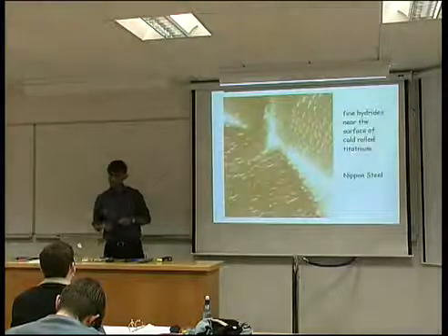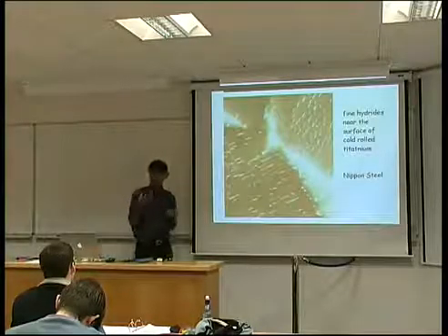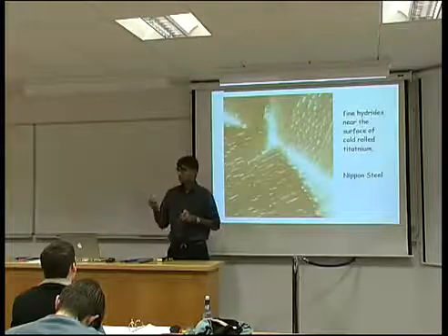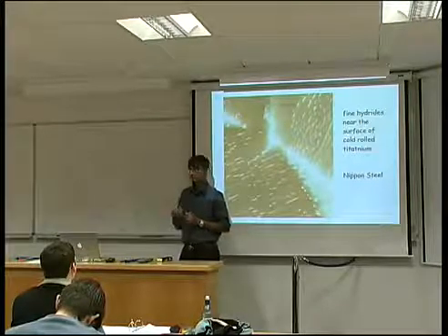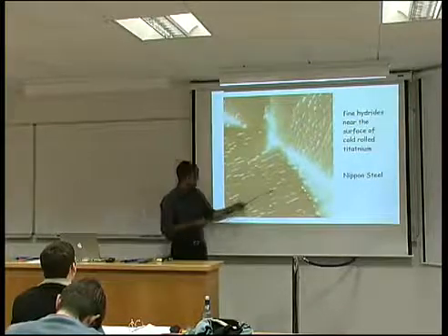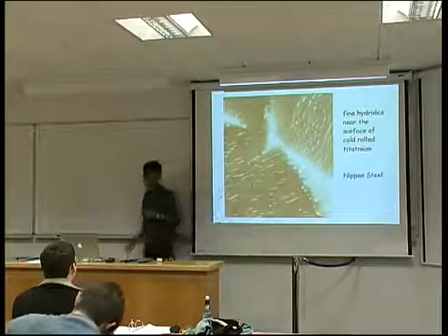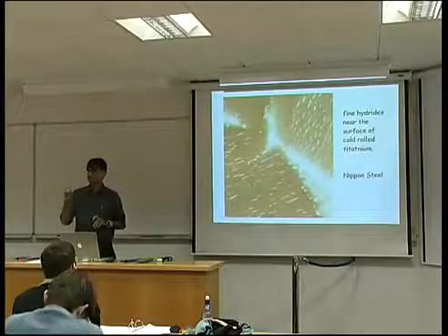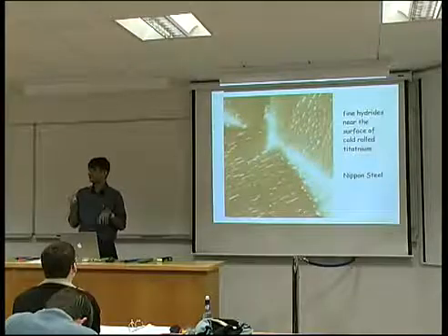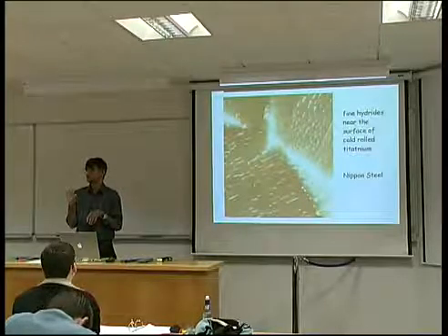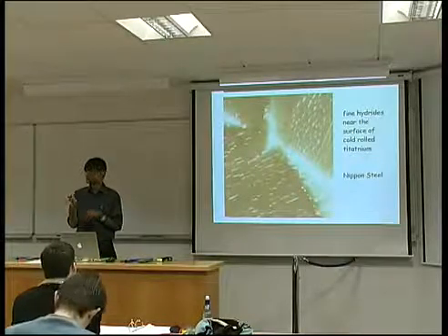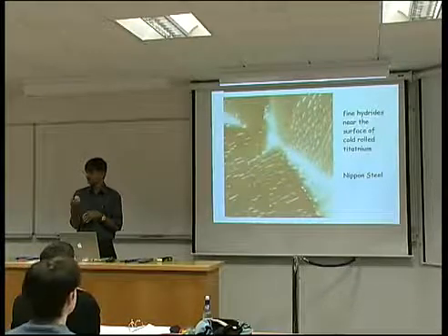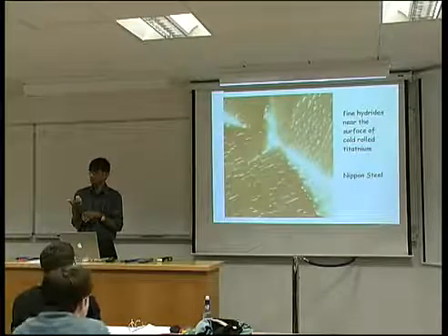Now, one of the difficulties is that when hydrogen enters titanium, it forms a hydride. So here is an example of the hydride. And that hydride is associated with a very large volume change, of the order of 20% volume change. So that severely embrittles the titanium.